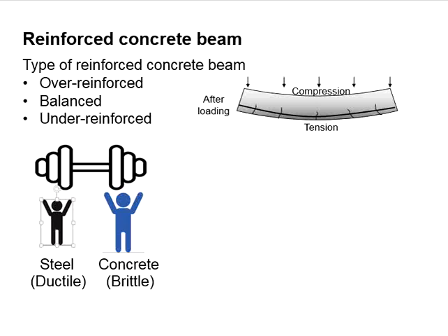Having this understood, now you know that when we want to design a member, we will need to always ensure that the reinforced concrete beam is under-reinforced. Under no circumstances should we allow the reinforced concrete beam to be over-reinforced. Knowing this, how do we cater for this in our design?